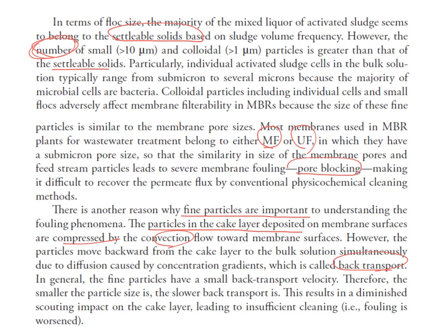So we normally do aeration or other flows to scour these fouling layers from the membrane, but if the particles are smaller, this scouring effect will be less significant.